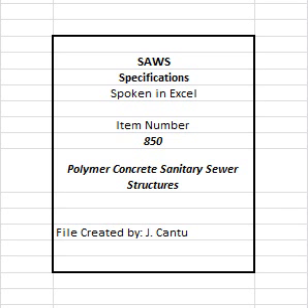A. Milestone 1, 40% of LS, structure setting to include for each such structure, excavation, compaction, base setting to include concrete base encasement with reinforcements, saw cutting of surfaces as required and connection of new or existing sewer pipes to the structure as described in this specification. After curing, the structure flow line elevation shall be verified by a licensed surveyor in the state of Texas and a certified report furnished to inspector, prior to payment and uploaded to CPMS.